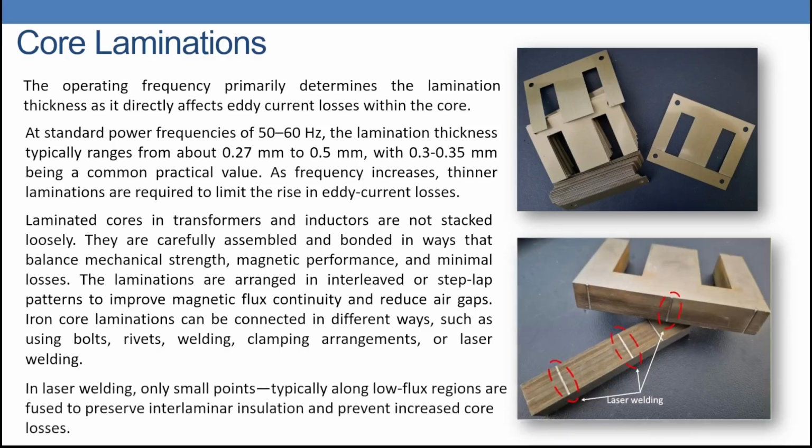Laser welding is particularly interesting because only small regions, typically areas with low magnetic flux, are fused together. Please look at the figure. This helps preserve the insulation between laminations and prevents an increase in core losses.